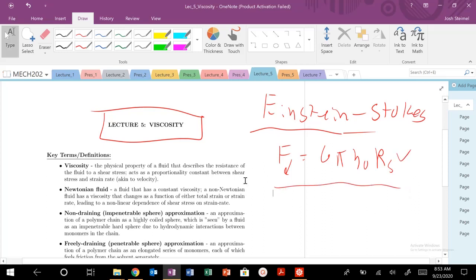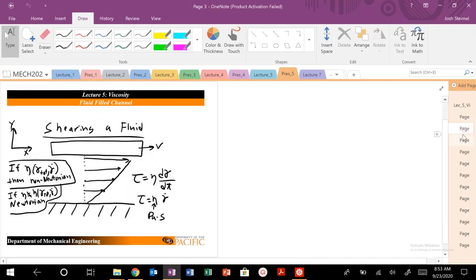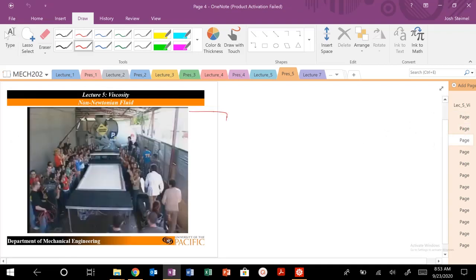So we're going to identify some unique and cool properties of polymers like we just introduced in the video the other day. In the video we introduced in class, which you can watch online, El Hormiguero, basically the anthill, a science TV show, I believe in Spain, we saw them run across this material. At high strain rates, it behaved like an elastic material. If our strain rates were low, we saw that it behaved like a viscous fluid.